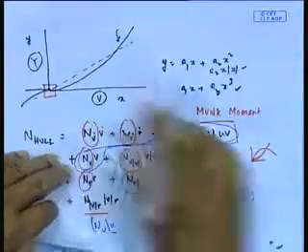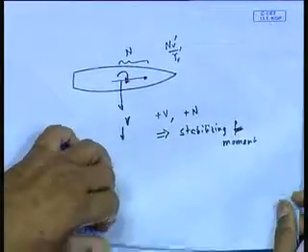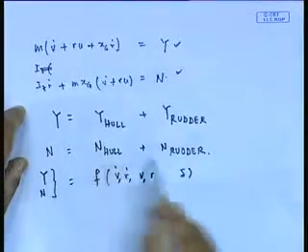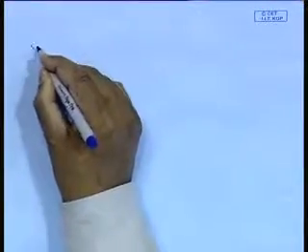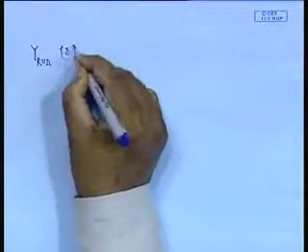Now, this is only with respect to the hull forces, but there is also coupling with respect to the rudder forces. Let me talk about the rudder for a minute, before I go to the captive test. So, let me look at Y rudder. This is a function of delta, the rudder angle.